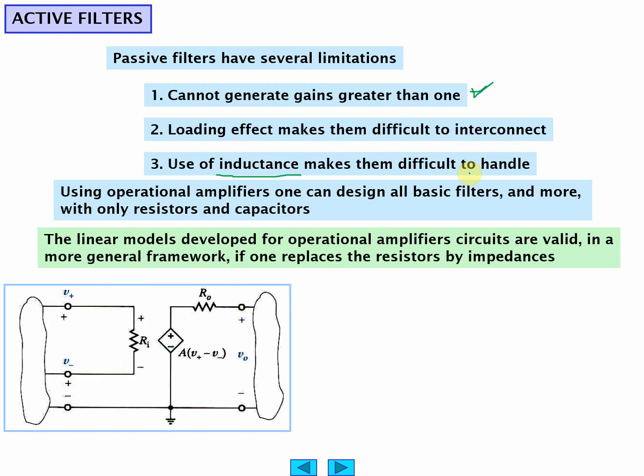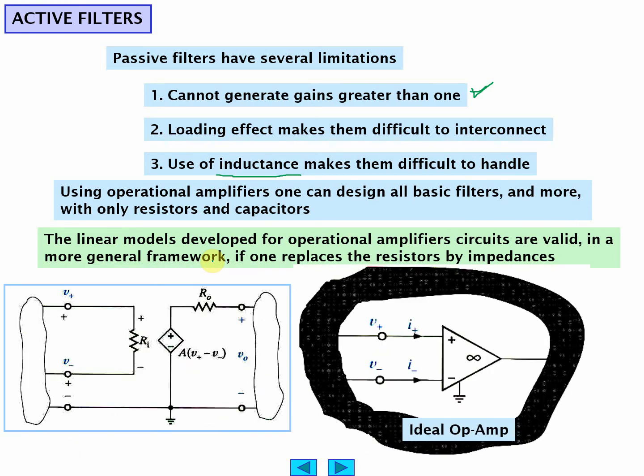Okay. So now here's the operational amplifier model in terms of dependent sources. Most of the time people use the ideal. They don't go to the real model. The ideal is so close to reality. The tolerance on components is going to be bigger than any kind of errors due to an op-amp being a little bit off.